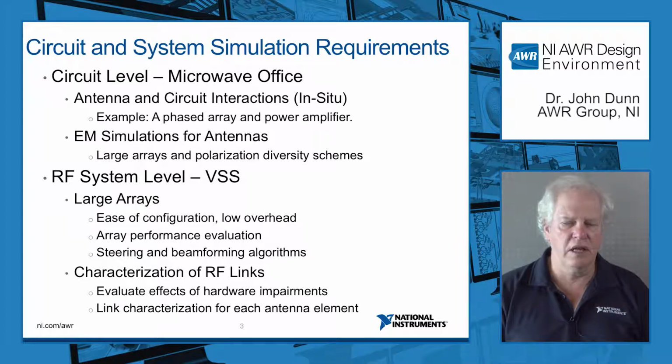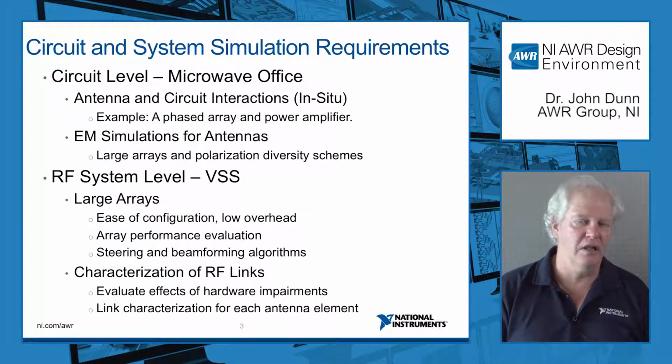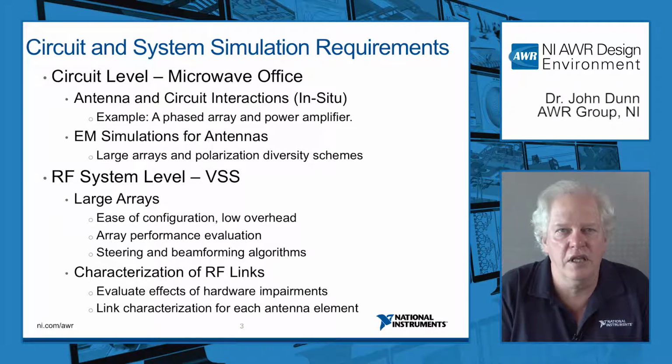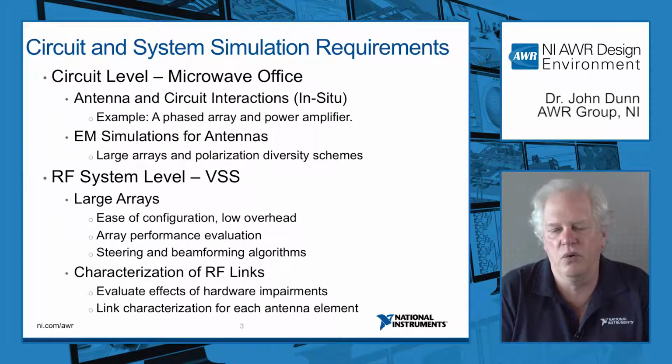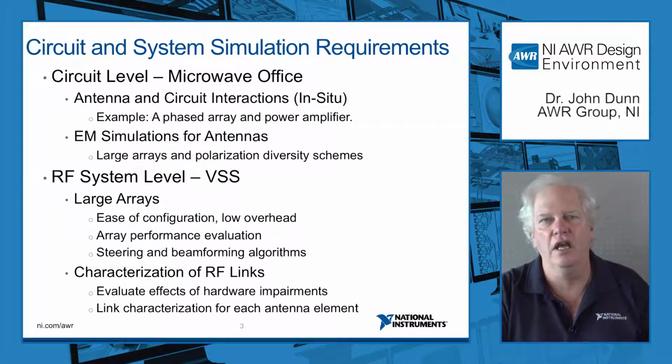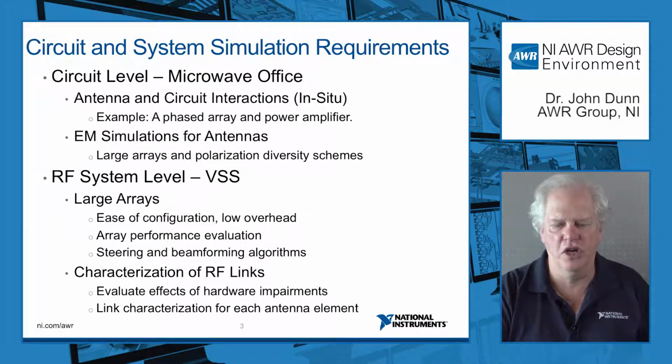But we at AWR with Microwave Office have to enable a couple features to support this too. And I want to talk about a couple of those today. So we're not actually going to talk about the EM today for the antennas. Rather, we're going to talk about the circuit and system requirements. So let's think about this for a minute. If you're going to support antennas at a circuit level, meaning you've run the EM simulation, and you now, of course, need to excite the antenna, excite the S parameter file, a couple of things jump up at you. And in particular, I'm going to talk about today something called in situ antenna issues with circuit simulators.